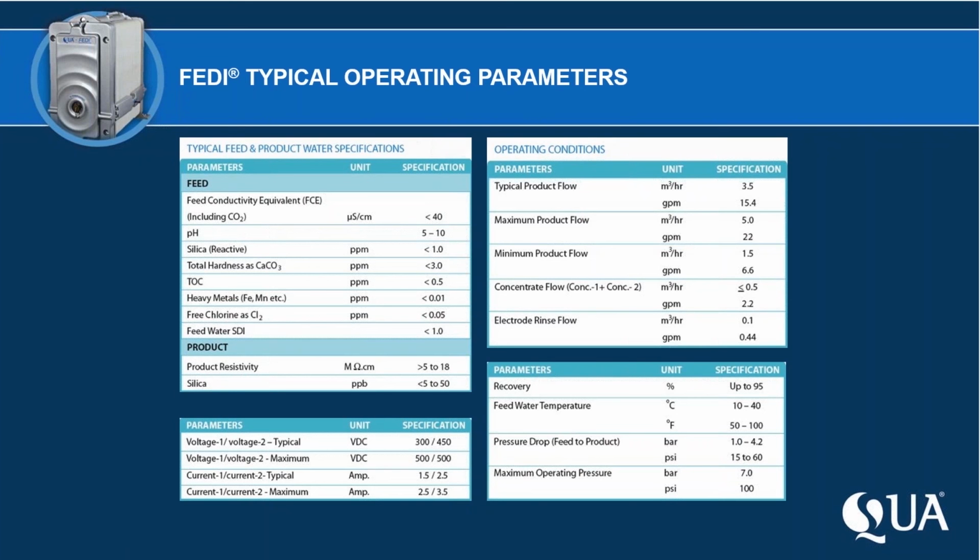So we definitely think chlorine and chloramine are probably one of the biggest problems you'll see in any type of EDI failure today: people not measuring or controlling their chloramine level or chlorine level. And even the RO membrane can become damaged.